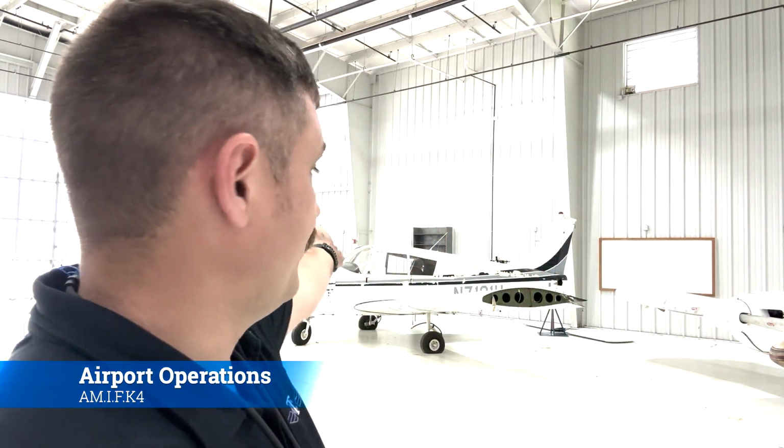always going to be the registration number, unless you're in some special vehicle, which you generally won't be. For instance, the airport has a truck you'll see driving around called Ops 1, so they'll say Tower Ops 1 or Ground Ops 1. If you're in the Lear, you're going to be 123 Charlie Kilo, and if you're in my plane, it's 1653 Juliet. If you're in the other Cherokee, that's 7131 Whiskey. Whatever aircraft you're in, you use that registration number as your call sign.